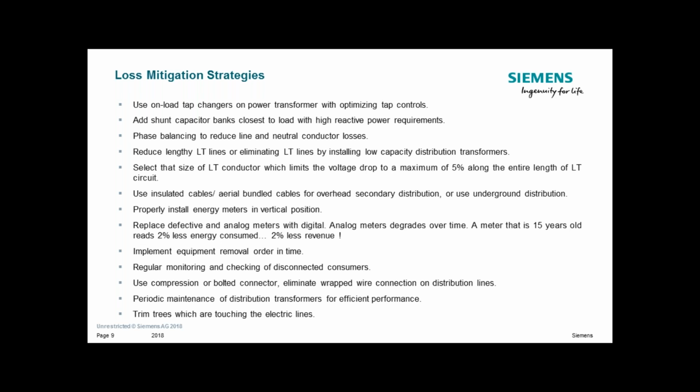Third, you can also adjust the loading on each of the three-phase conductors, because if you reduce the unbalance between the phases, there will be less current through the neutral, and if there is no current through the neutral, then the losses will be minimized.